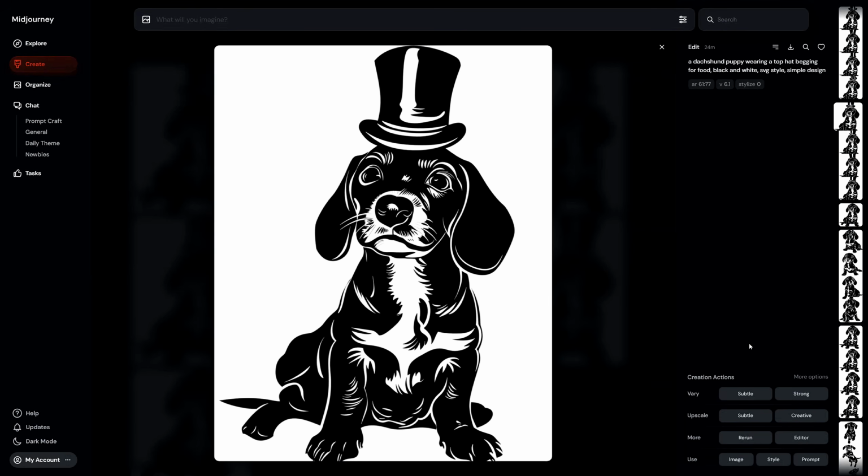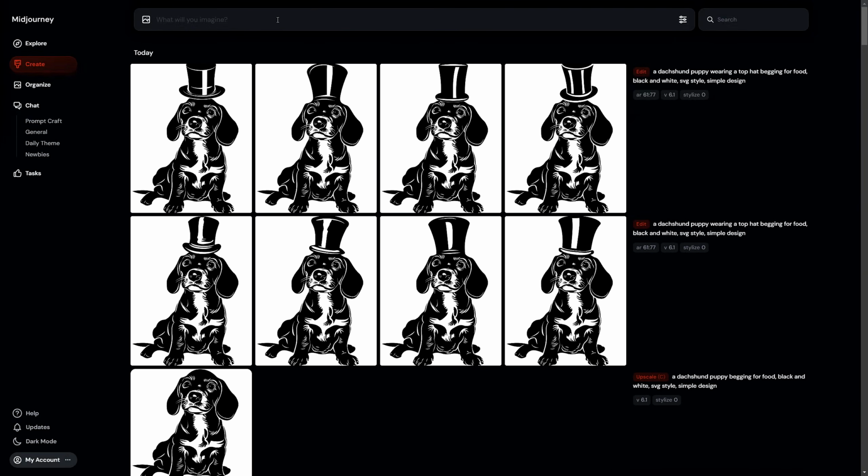Alright, I wanted to quickly touch on style references. Even though the main course for this video is about utilizing Midjourney for 3D printing, I still thought I would quickly touch on style references. I have come across some styles that add an artistic flair to our black and white designs. Rather than using an image reference, Midjourney has a feature called style reference seeds. You can use a style seed with your prompt to get a new creative result. The way you do this is to include a --sref and a number between 0 and 4 billion.